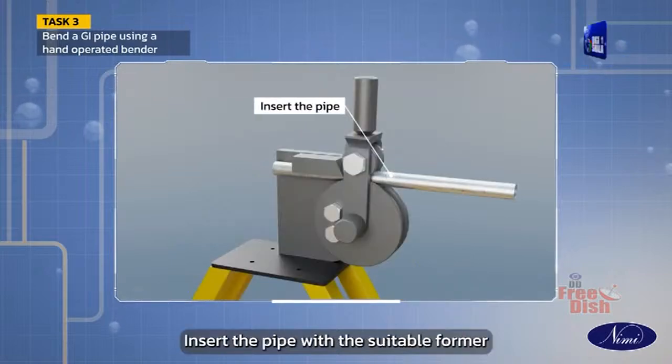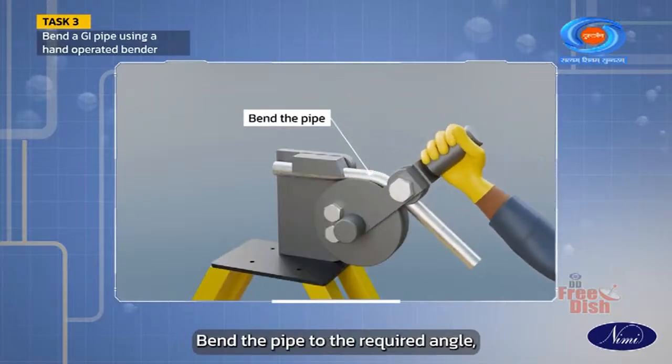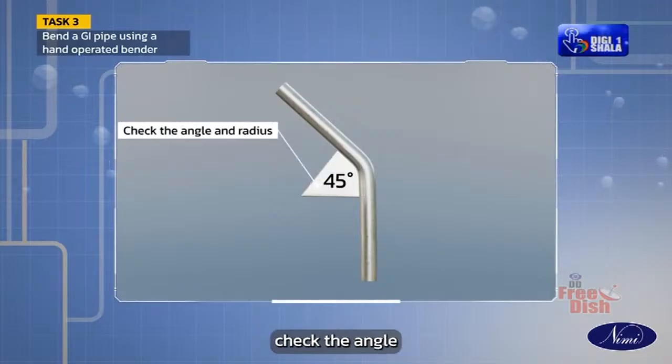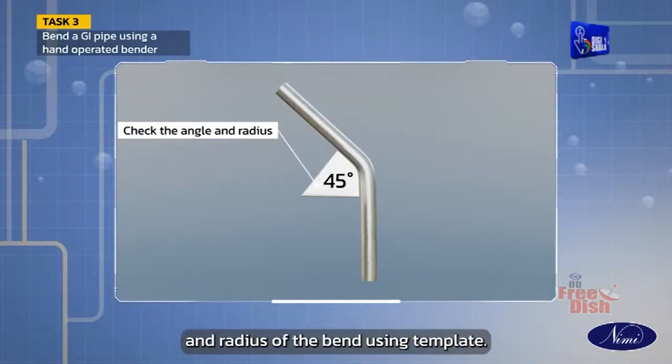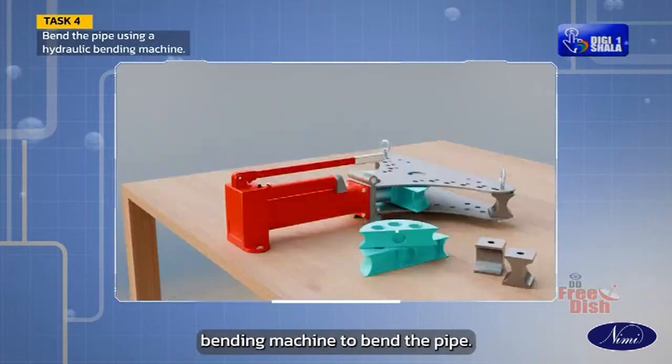Insert the pipe with a suitable former. Push off the leverage handle and give gradual load to the machine. Bend the pipe to the required angle. Check the bent pipe. Check the angle and radius of the bend using templates. Now let us use a hydraulic bending machine to bend the pipe.